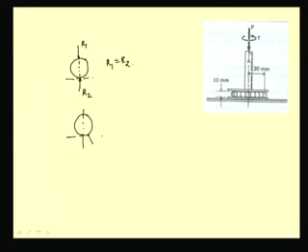So this reaction shifts to a point, the distance to which it moves is equal to the rolling resistance, that is 0.0127 mm in this case. So the force coming from the top face, which is R1, is also displaced by a distance of 0.0127 mm. The radius of these ball bearings is 5 mm.